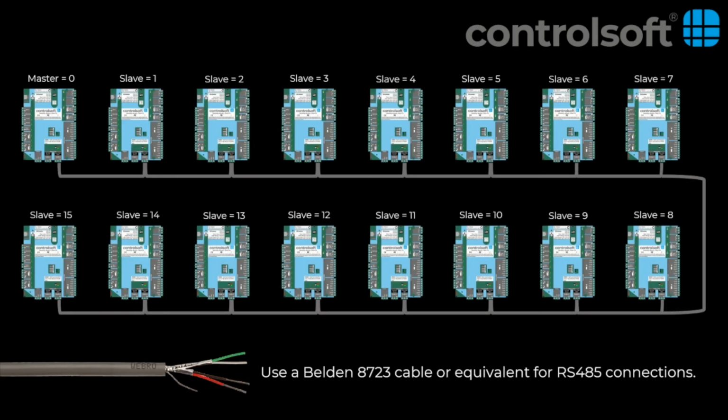The main benefit of using a slave iNet controller is in situations where there is no IP network infrastructure available in the location where you want to install additional door controllers. A Cat5 network cable will only typically reach up to 100 meters point to point, but when using RS485 you are able to connect devices up to 1 kilometer away from the master controller.